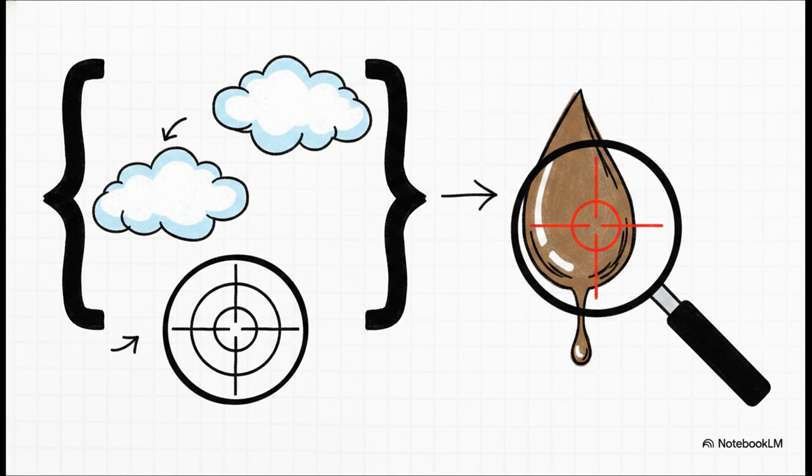But there's a fascinating little caveat here. Ideal gases, like air, actually give us a bit more leeway than heavy oils. For an ideal gas, you have considerable latitude in your temperature property determination without totally throwing off your final convection coefficient. But for viscous liquids or petroleum products, no way. You need absolute, strict precision there.